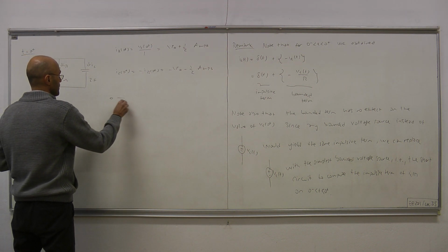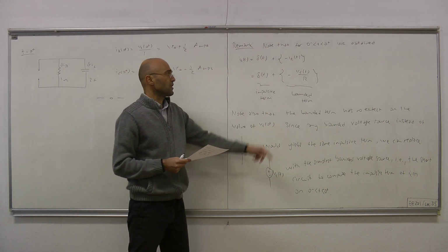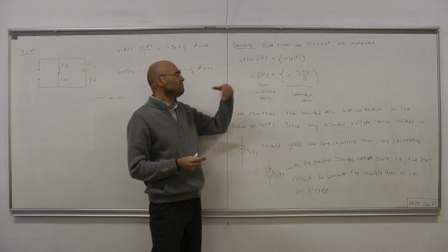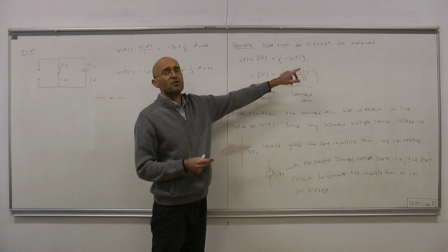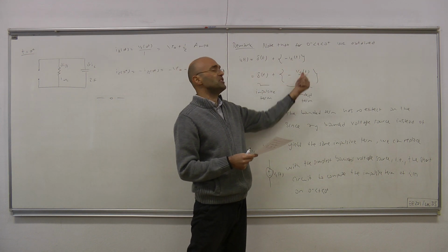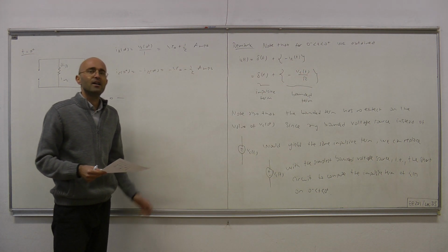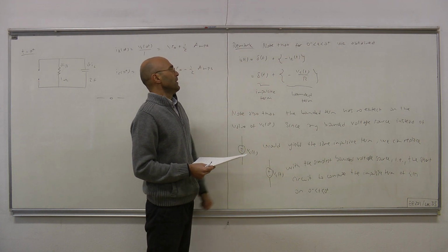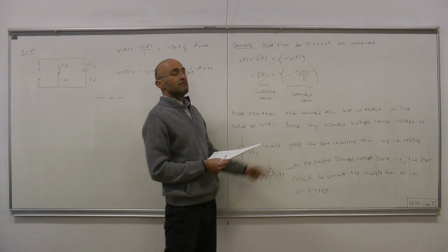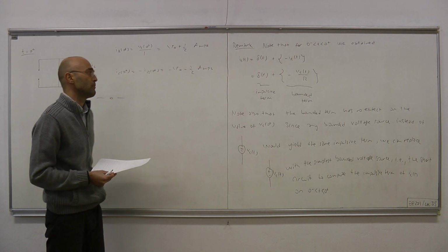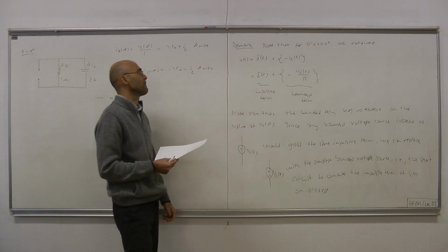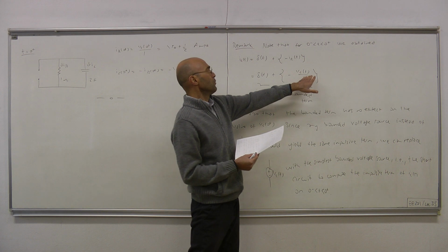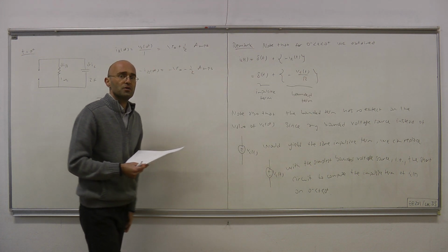So let's revisit our example with this suggestion, which says that since the only thing that matters about v_C(t) is that it's bounded, it doesn't make any difference, as far as figuring out the impulsive component of the capacitor current, what voltage source you choose.